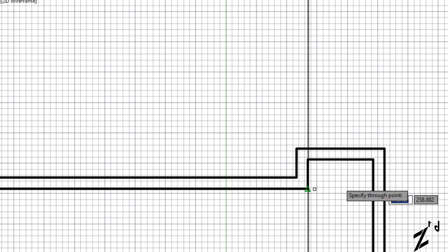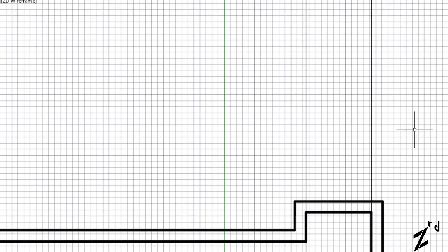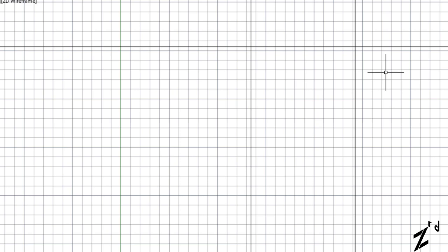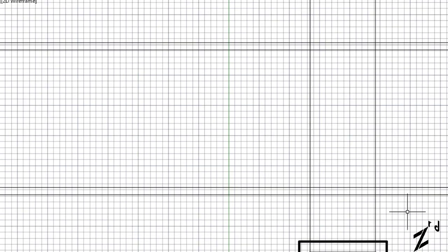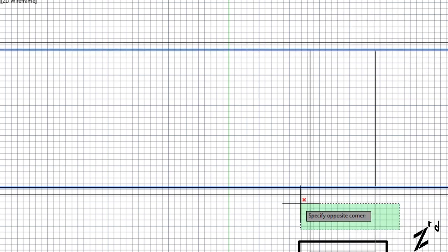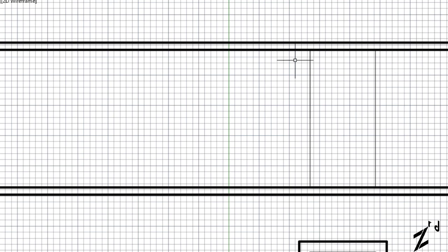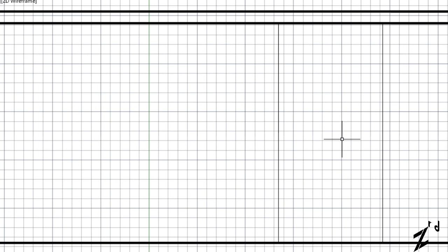So just drawing an elevation here, projecting that up, XL horizontal, offset by, let's say our floor to floor is 300. This is in centimeters, sorry. So 300, and let's say our slab on top is 15 centimeters. Our slab below is 15 centimeters also. So this is approximately our elevation. Let's trim this. So this would be the elevation of our wardrobe.